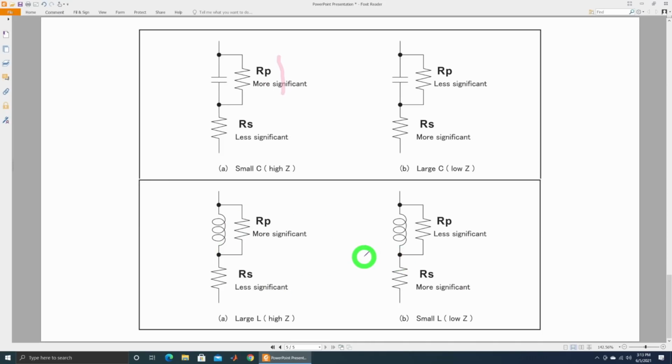Now it becomes even more complicated across frequency, because everything has its associated inductive and capacitive parasitics too. So this element in reality also has some capacitance in parallel to it, and it may even have capacitances to ground and so on. And these models become more and more complicated and have to include multiple devices, components at the same time if your frequency is very high.